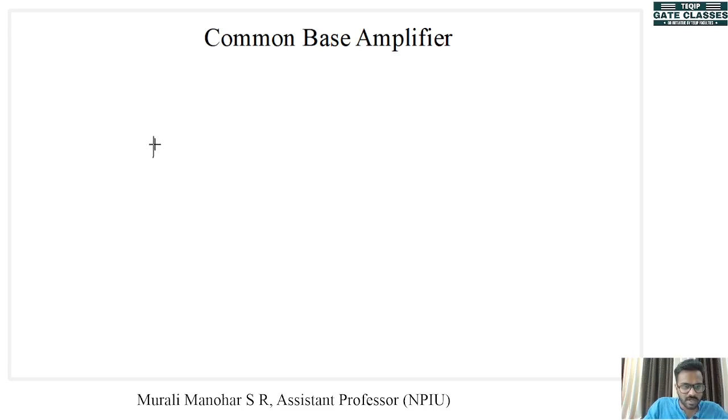So there is our transistor with its emitter, base and collector. We are applying fixed bias here. So there is our RC. Here we have VCC. Here we have RB. Now here we have a coupling capacitor, and now this is connected to the ground. This is RB, this is RC. Now there is an emitter resistor here, which is called RE.